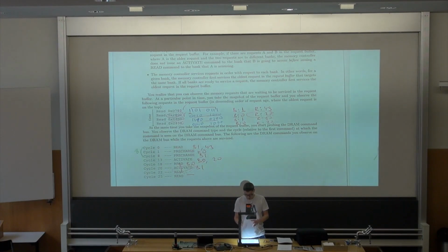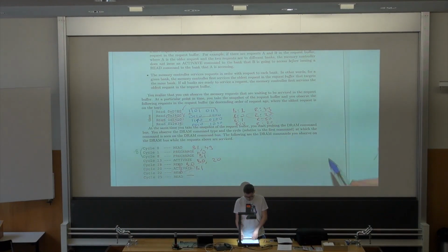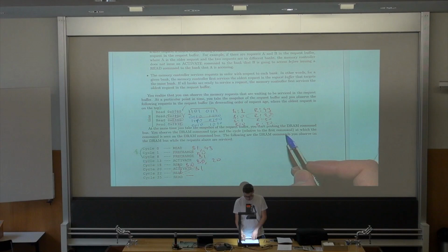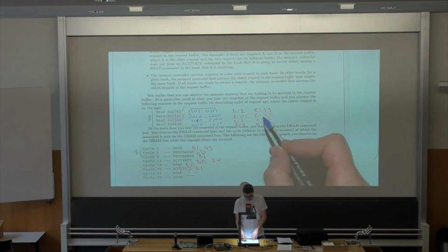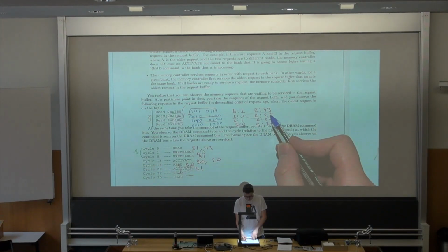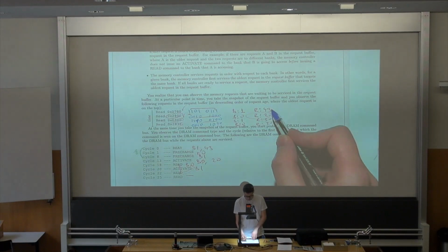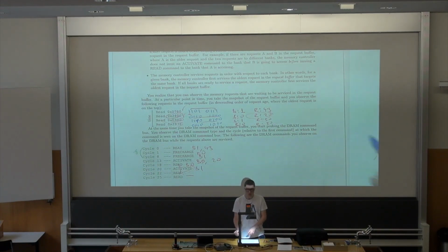All values from 0 to 20 are equal, so they will all result in exactly the same execution time when we use TL-DRAM, because we don't have any rows in between. Okay, so the ranges we have to check for n are one value between 0 and 20, one value between 20 and 43, then 43 to 50, and then more than 50.